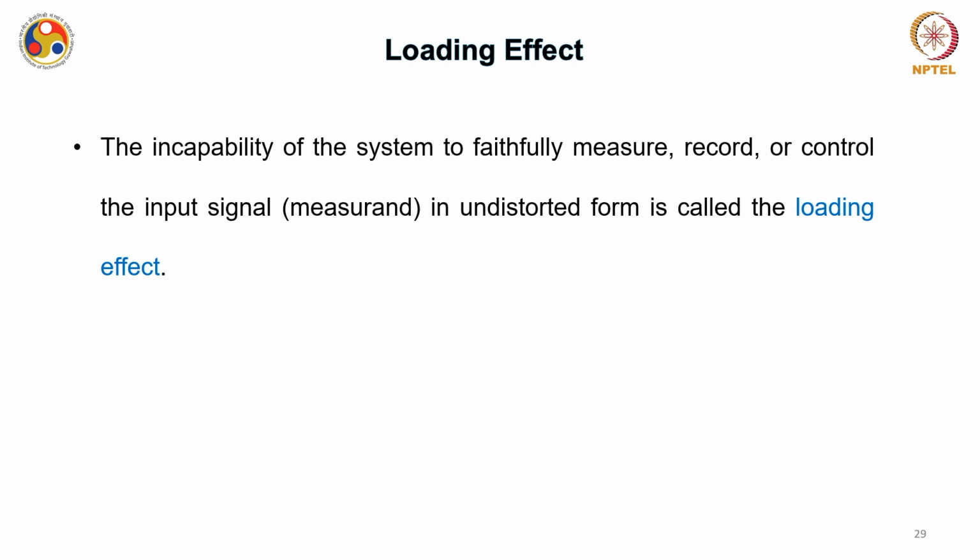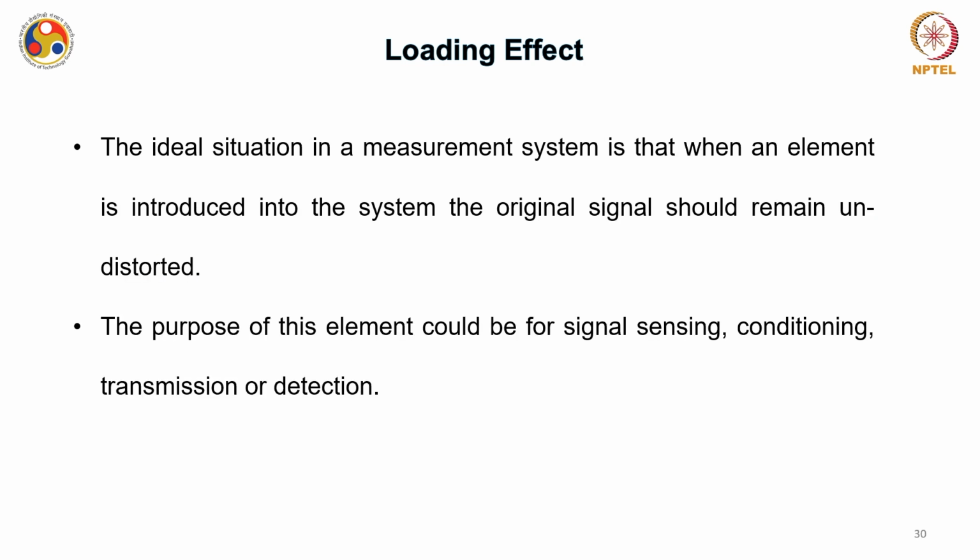The ideal situation in a measurement system is that when an element is introduced into the system, the original signal should remain undistorted. The purpose of this element can be anything: signal sensing, conditioning, transmission or detection. If there are certain changes, it is causing a loading effect to the measurement system.